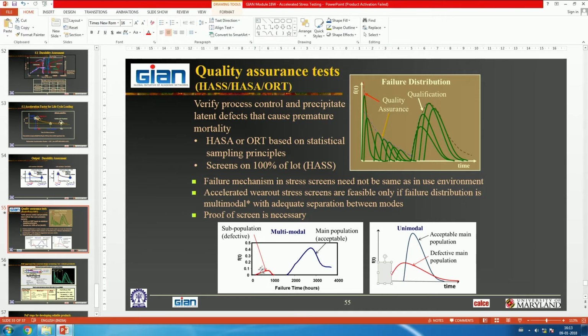So unless there's reason to believe, and for that you'd have to go back to the manufacturing process, you'd have to root cause, you'd have to convince the buyer this is where the defects came from, and look, that was only one shift. The rest of my pieces are all likely to be in the blue curve. That one shift would have produced a few bad ones. Let me screen those out. And here's my proof that there's sufficient life left after the bad ones go. Unless you can answer all of those questions, the buyer will not let you screen it. Okay, so that's how screening works now.